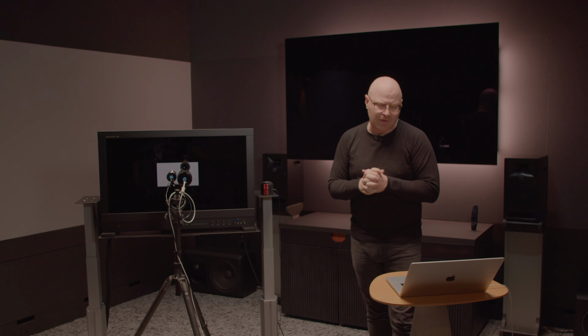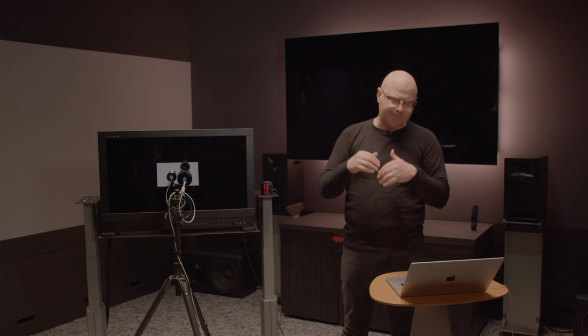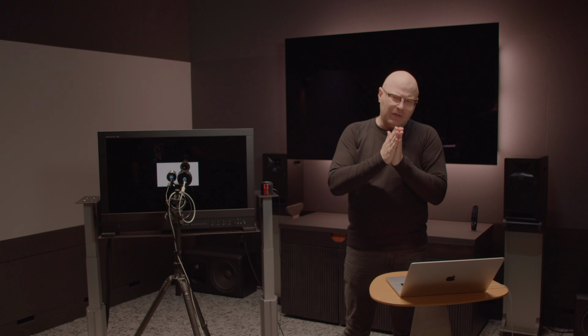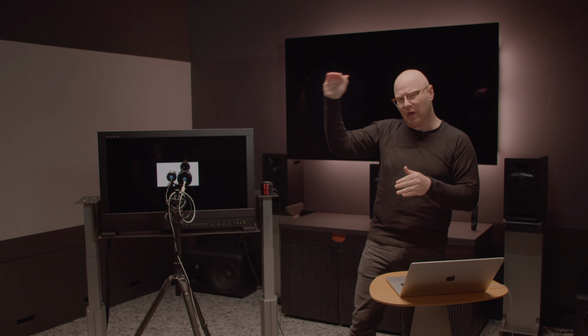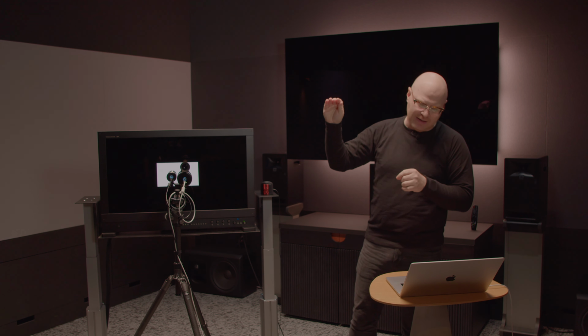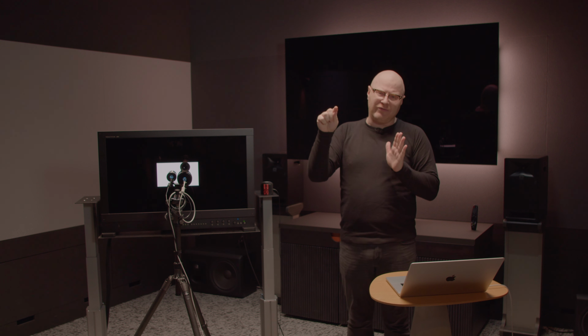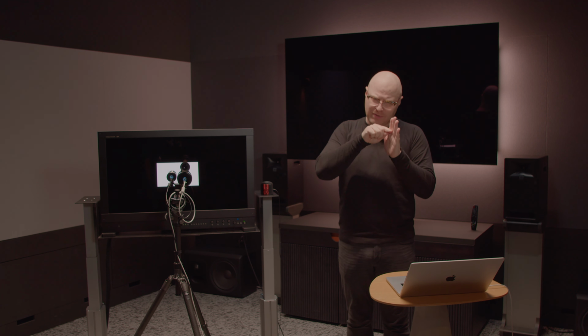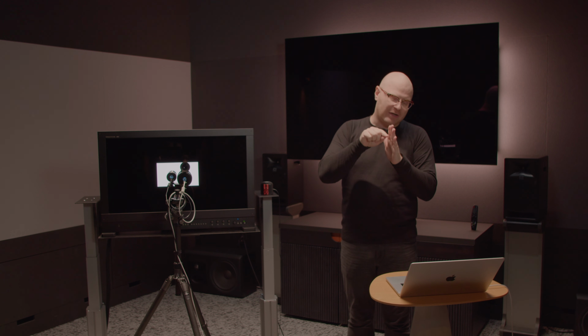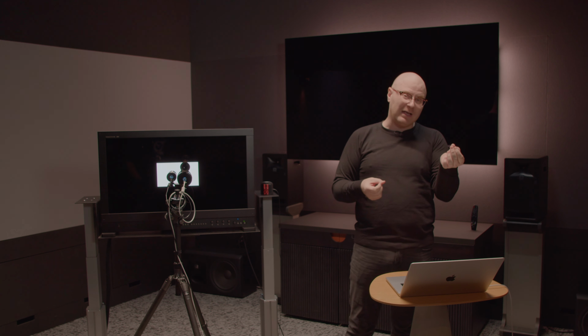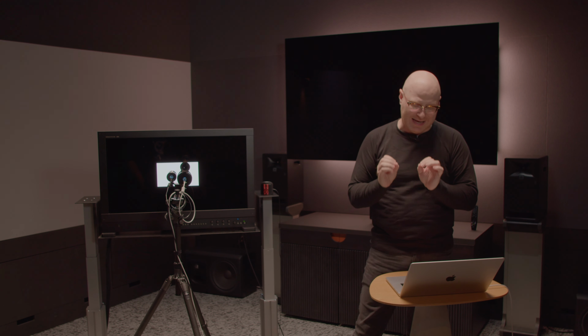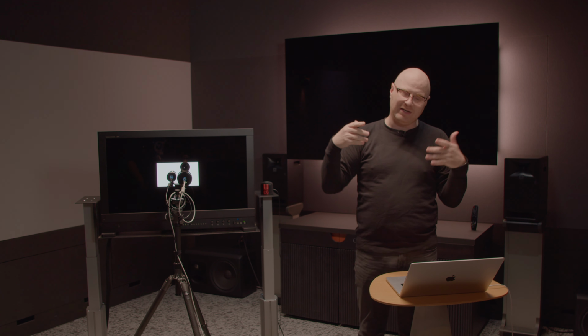Now, one of the things that's very important when calibrating an HDR display is that we don't really want to target the peak luminance and the white point as our primary. What I mean by that is we want to make sure the EOTF, the SMPTE ST 2084 PQ, perceptual quantizer tracking, is actually tracking the curve very well, because HDR is what we call a bit per nit. A certain bit level is supposed to equal a certain light level. It's very much specific in how it works, versus a relative method such as gamma tracking in SDR, where 2.4 is more of a relative curve than it is an absolute curve.